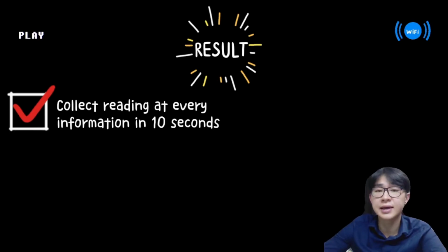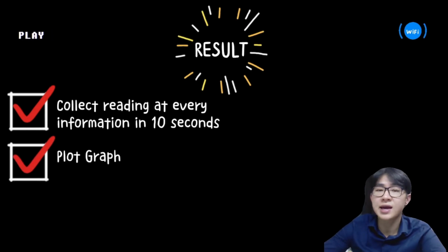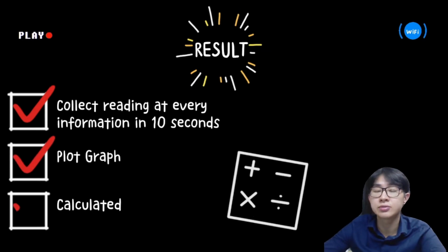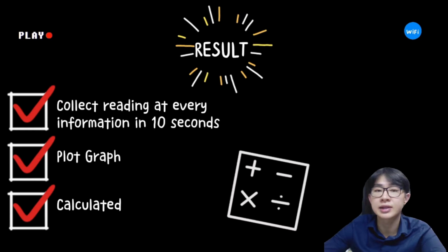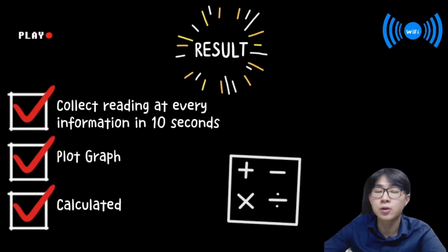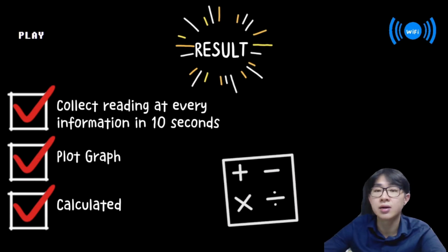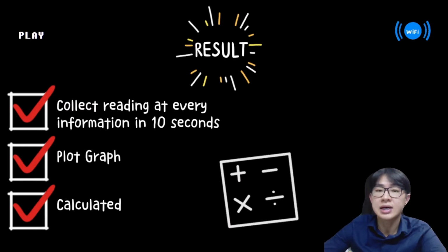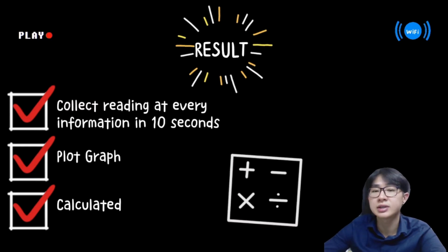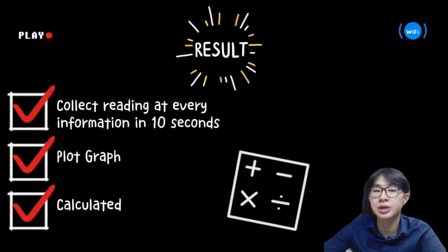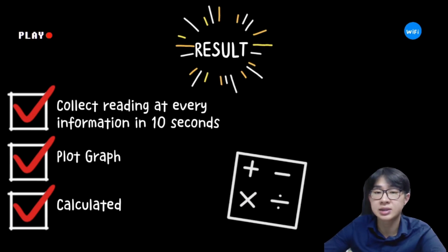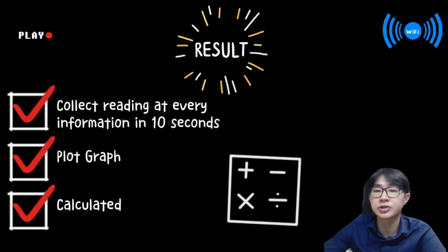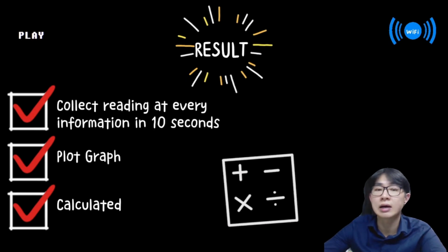As soon as I get the RSSI values, I can analyze them by capturing the reading every second within the time period. Therefore, I plot the graph to see the data I have taken from Ubidots. Based on my readings, I have to calculate a few terms such as standard deviation, mean, mode, median, and variance. From the data, it seems that all values are negative, so I change them to positive numbers to make my calculations easier.